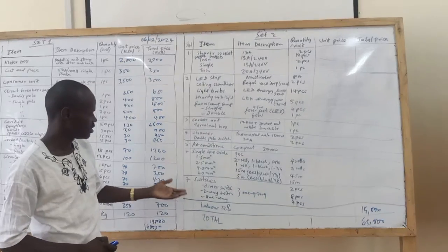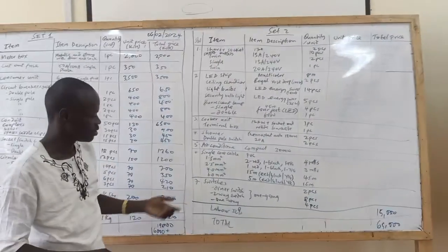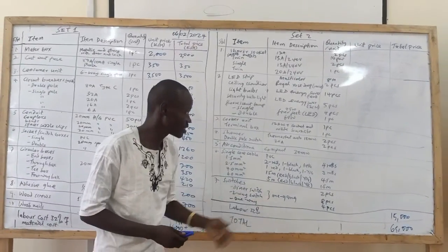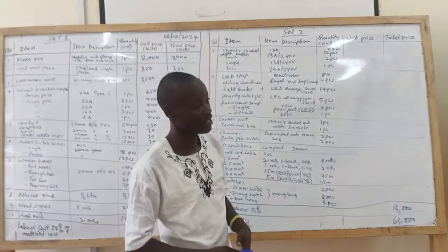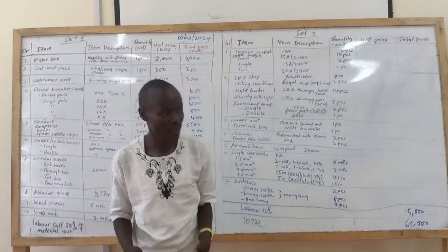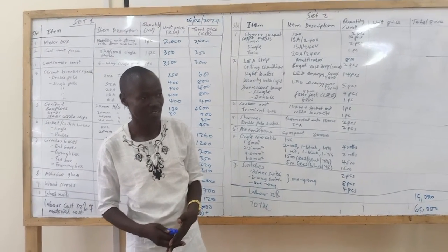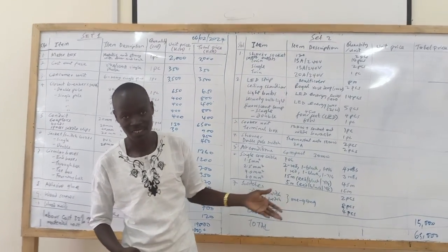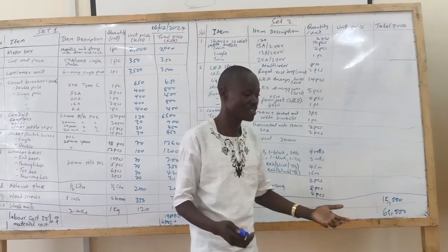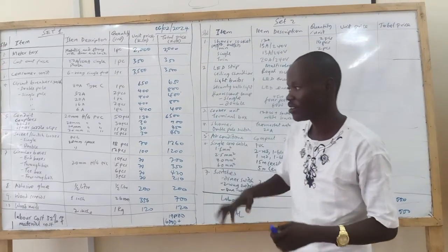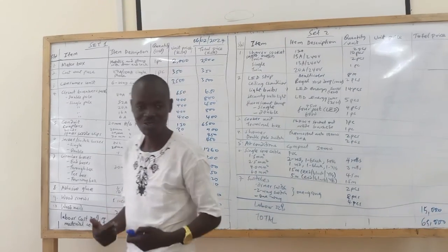And then also you need other additional tools like the testing tools. When you're cutting out the final set, you need testing tools. In this case, you don't need a voltage tester because there's no power yet. You might need things like a digital multimeter. You might need an ohmmeter to measure the resistance and continuity. So by doing all that, you'll be doing the right thing. Remember, all this is just you're preparing. You're not actually doing the actual installation.